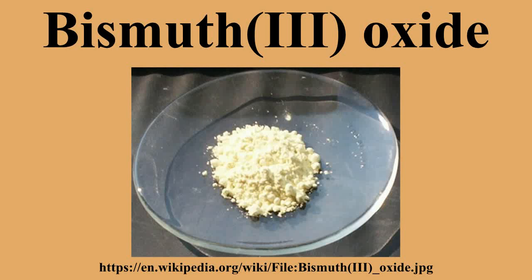ionic conductor. In addition to electrical properties, thermal expansion properties are very important when considering possible applications for solid electrolytes. High thermal expansion coefficients represent large dimensional variations under heating and cooling, which would limit the performance of an electrolyte. The transition from the high-temperature Bismuth Trioxide to the intermediate Bismuth Trioxide is accompanied by a large volume change and consequently, a deterioration of the mechanical properties of the material.